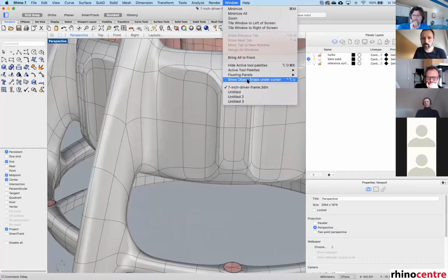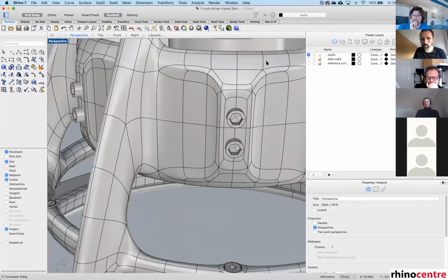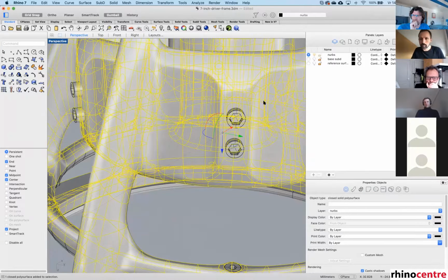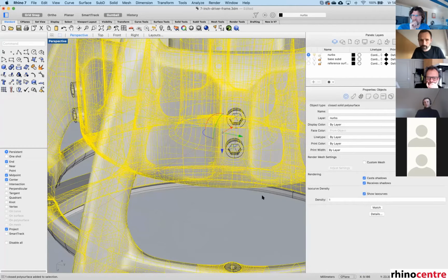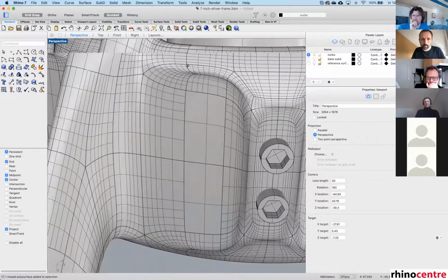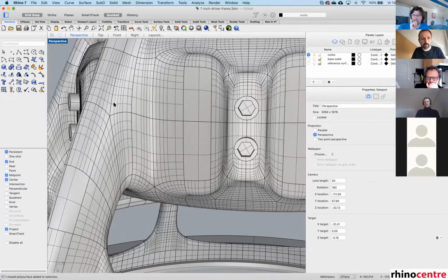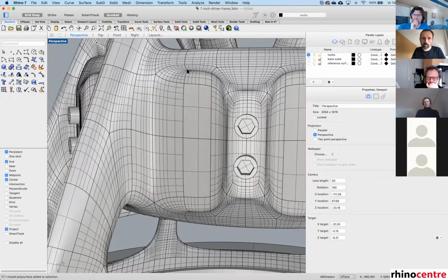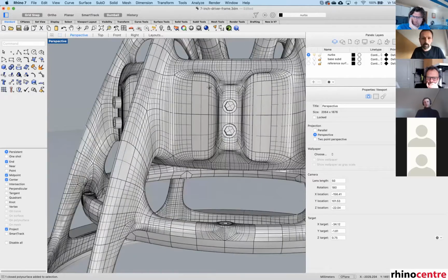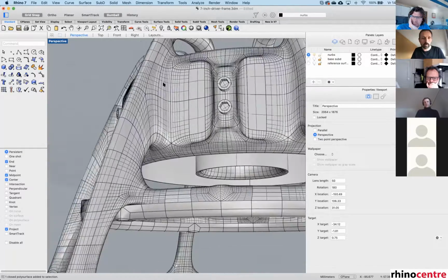So let's have a look at that Nurbs model again. I'll turn on the ISO curve for this one. So you see that here we have again 4-sided patches, and this is also divided in 4-sided patches again. And the continuity at those star points is a problem at the moment.